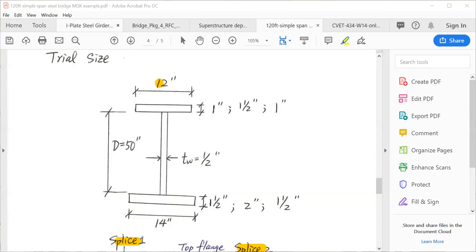Okay, so there are 4 options: girder system rating, girder system design, line girder rating, and line girder design. I will explain each one, and we will use the girder system rating. This will rate all those girders, including every girder line, like exterior girder and interior girder, and will give you the maximum performance ratio.